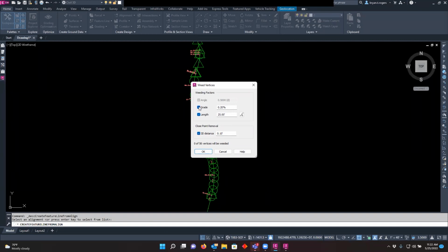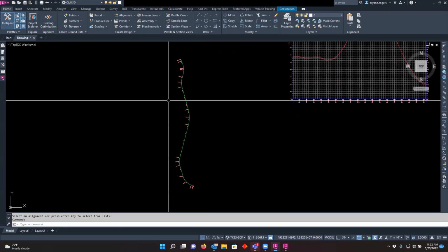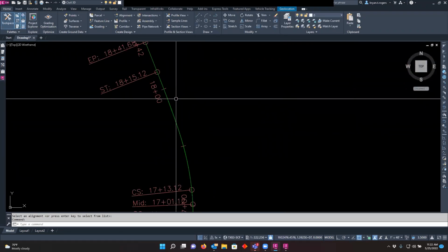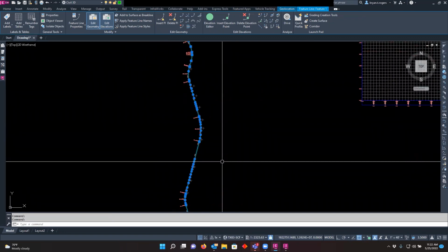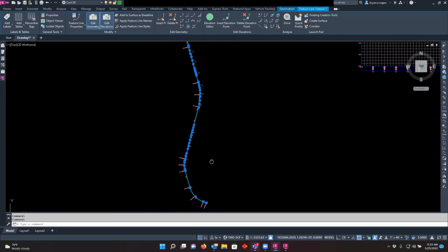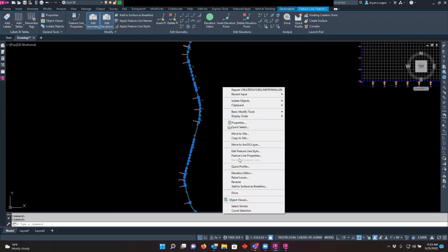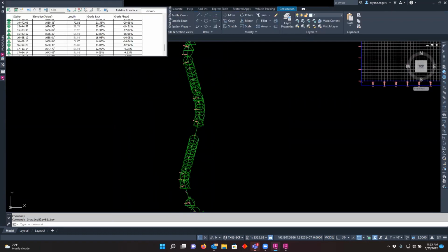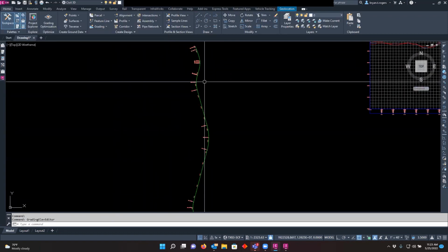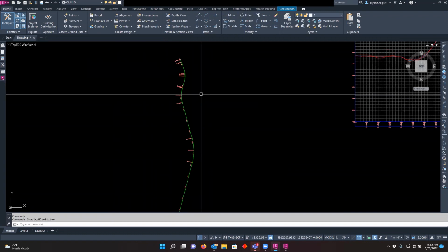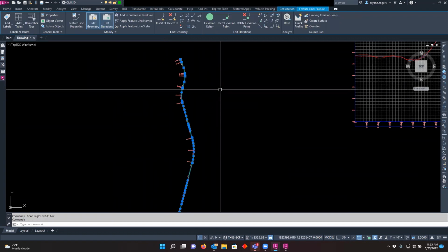And I don't like to weed anything out, but we're going to just go ahead and let it be like it is because it said 0 is weeded out, right? Now, if I click on this, you'll see there the elevation points along this feature line. So there you'll see the elevations along it. It extracted all those elevations. Fantastic. We love it. Now, another important thing here to keep in mind is this feature line.